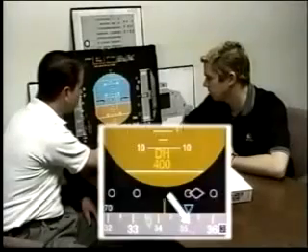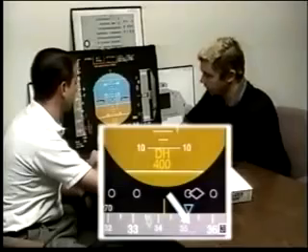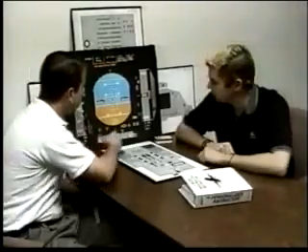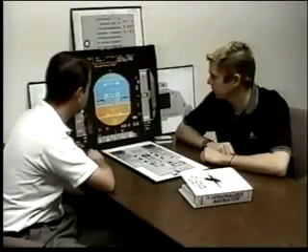What about our magenta sword or dagger here? That's the ILS course selection, and this is on scale, this is off scale. Again, how would you get this display? The ILS push button has to be selected on. Good. In which case, as you said before, we get our raw data glide slope and localizer. Right.